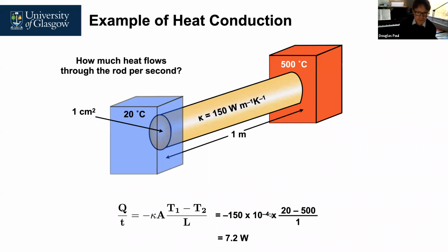So if you're taking a difference, it doesn't actually matter if you convert it into Kelvin. However, if you're looking at something where it's absolute temperature, so for instance, for some of the thermodynamic relationships, so if it's PV equals nRT, T in that case you have to do in Kelvin, because it's the only way it matches with the rest of that equation.